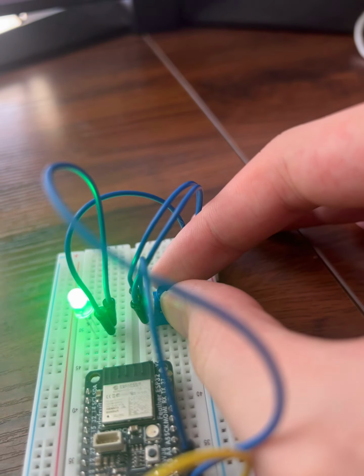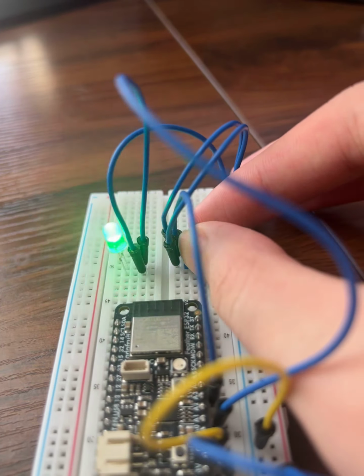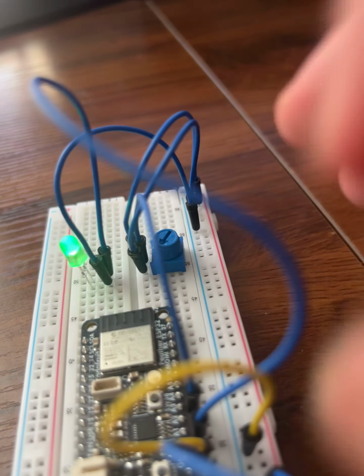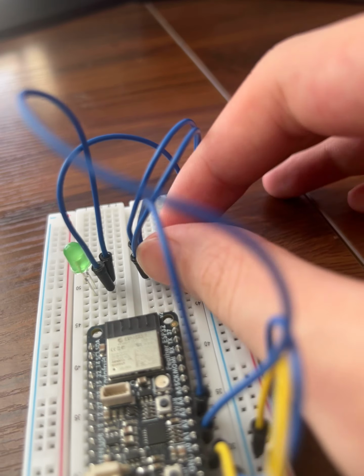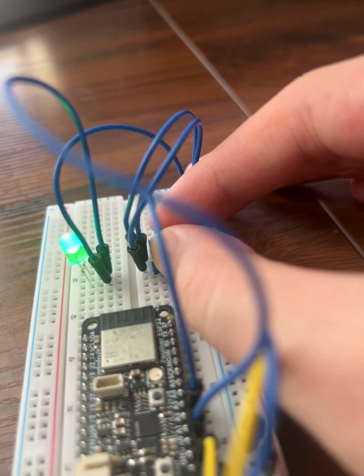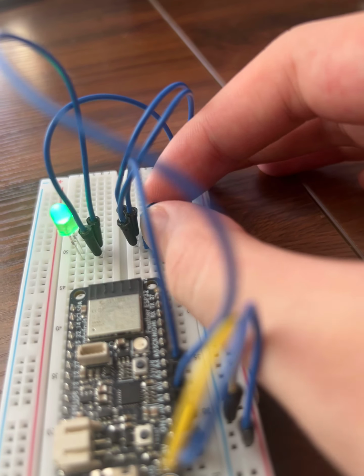But if I turn down the potentiometer for a bit, you will see that it's getting dimmer and dimmer while toggling at the same frequency. And I'll set it to a bit dimmer right now so that you can see. Okay, so now if I press the button again, as you can see, it's blinking, but the brightness doesn't change at all, so the duty cycle remains the same. It's just the frequency changed, which is required by the code.